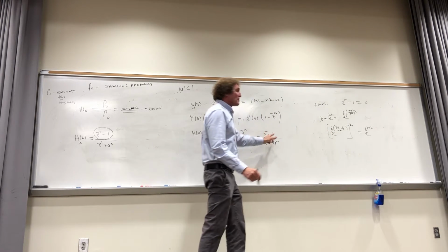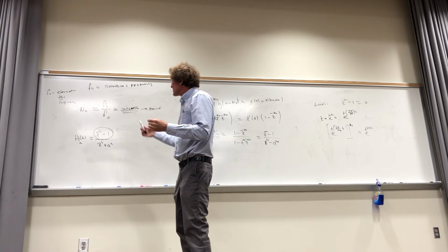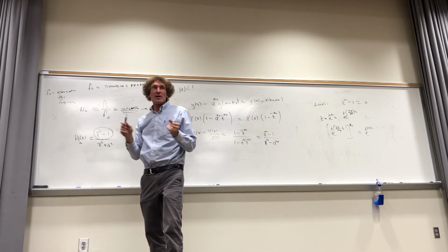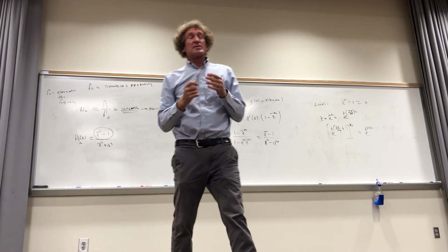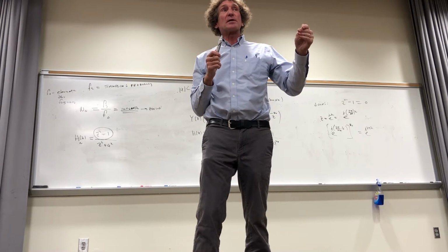And then you have 1 minus 1 is 0. In other words, you have zeros there. And that's what you want. You want the 0. If this is an integer, you want to get rid of this frequency, I'm sorry, get rid of F naught. If it's an integer value, then you can with just this. And not only that, it gets rid of all the harmonics.